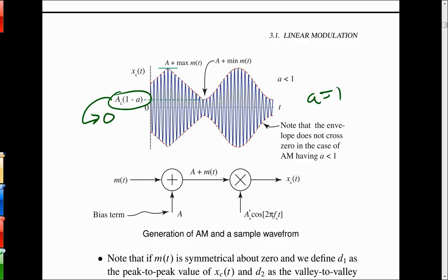But in an AM radio, if the transmitter is going over 100%, you get a very distorted reception because basically you're getting the signal clipped. Because if the envelope detector works by clipping off the positive half, and if the waveform is passing negative, that gets clipped off. Actually what you get is this comes down and then the other piece comes up. So you'd get something like that.